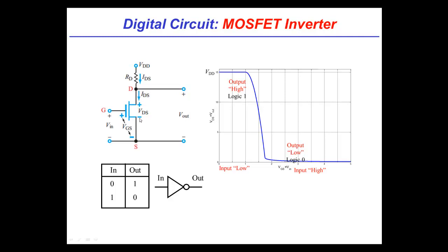So now it's going to run a whole mess of current down here. Don't worry about the numbers for now. It's just a large number. And that large number times this resistance is what? The voltage across the resistor. Right. So what you're saying is there's going to be a really large current, which means there's a large voltage drop. So it effectively is like pulling the output to ground. You can think of it as a voltage divider, essentially, where RD is some value, but the transistor acts like a really low resistance. That's exactly right.